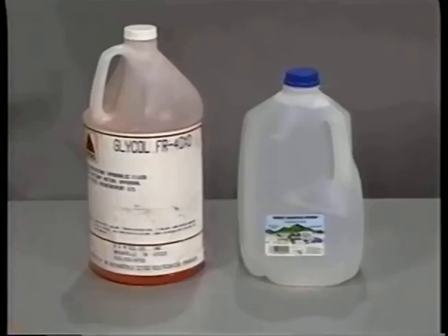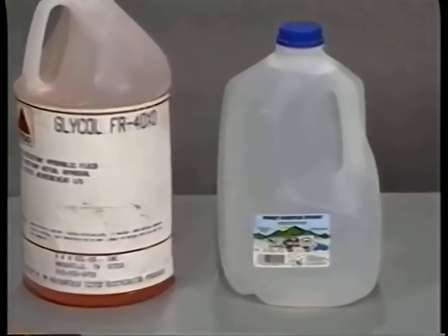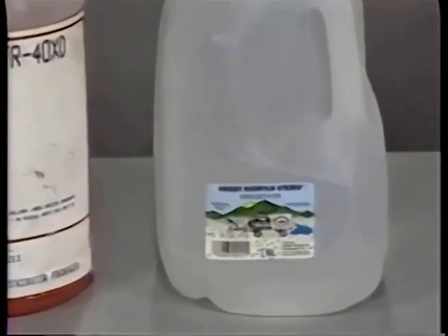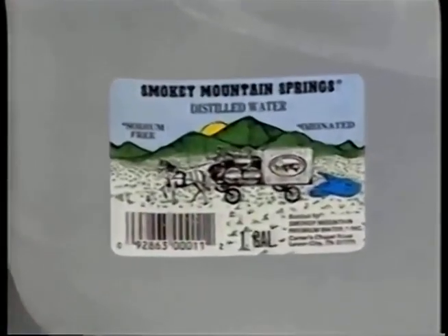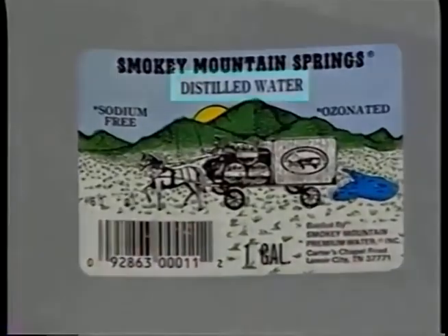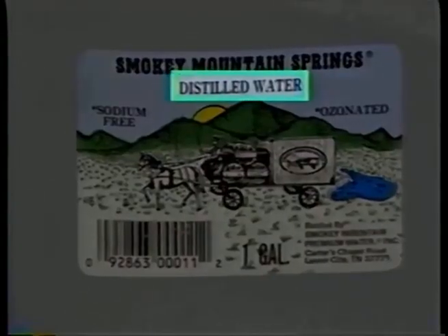But be careful where you get the replacement water. Common tap water can contain chemicals and solids that can damage a system. If you have to add water to a water glycol fluid, make certain you use distilled or deionized water.